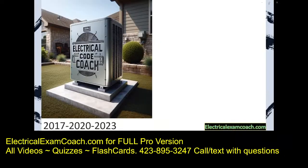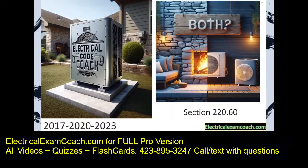Hey everyone, welcome back. I am the Electrical Code Coach from electricalexamcoach.com. Today we're going to be calculating HVAC VAs for our heating, venting, and cooling. The only code that we need to be familiar with is 220.60, and that's talking about non-coincidental loads. Let me explain what I mean. Usually in a typical house, you're not going to be running the heating and the cooling at the same time. So the code has made provisions for our whole house load calc that we only have to count the larger of the two. Let's get to it.